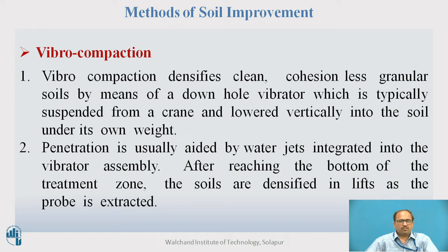First one is Vibro-compaction. Vibro-compaction densifies the clean, cohesionless granular soil by means of a downhole vibrator, which is typically suspended from a crane and lowered vertically into the soil under its own weight. Penetration is usually aided by water jets integrated into the vibrator assembly.